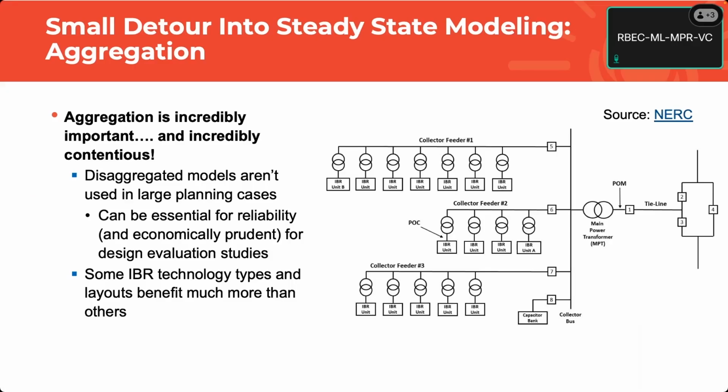No, that's a good opinion. The other piece of that is the things I just talked about: partial tripping because of voltage drops, reactive capability because of voltage drops. You don't need EMT to study that. You can do that in the steady state. You can do that in kind of a pseudo steady state if you're using something like PowerFactory. And you can do it with a transient model if you really want to.